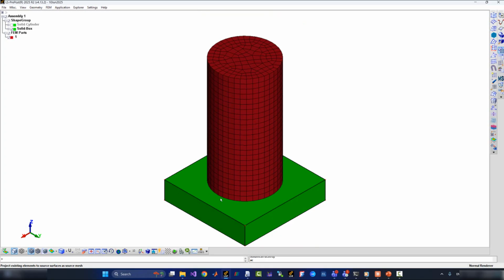I'm going to use a larger element size of 1 inch for the bottom plate. The bottom plates won't have any regions of large strain gradients or whatever. They are bound to remain linearly elastic with small strains. So we can get along with a much coarser mesh for this.